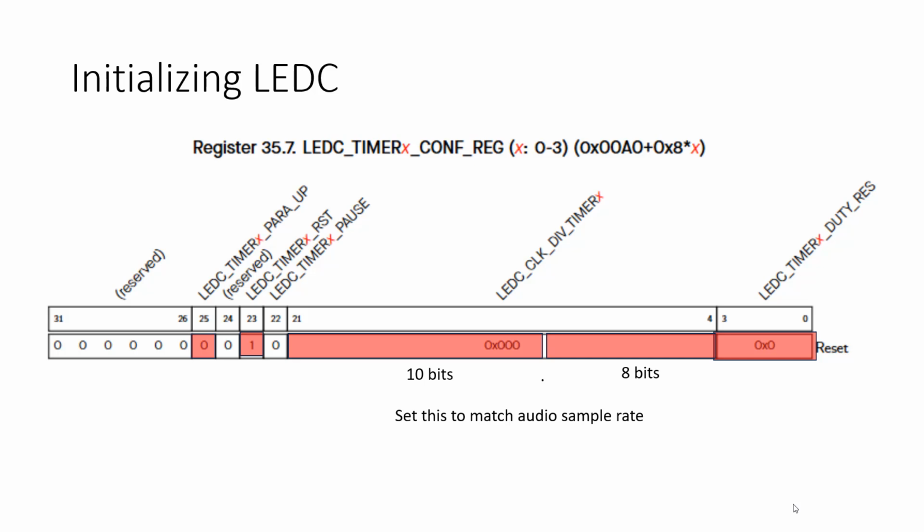So this is actually an 18-bit field. This is a big field, but it's using fixed point representation. Do you guys remember fixed point? We covered that in 611. So the idea is that there's 18 bits here in total, but 10 of the bits are whole bits and 8 of the bits are fractional bits. Okay? So this is the divider, the clock divider, right?